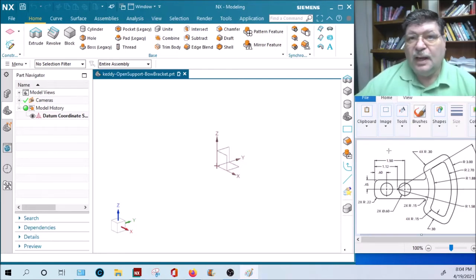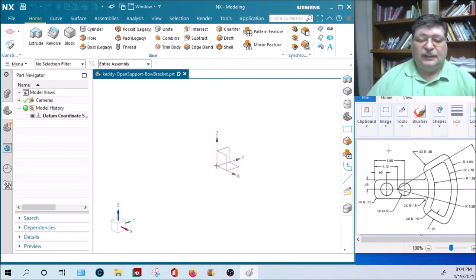Here's why. In order to just draw one line on NX, you have to make a starting point. That takes 2 dimensions, 2 constraints to start the point, to define the point. And then the other point of the line is another 2 points, x, y coordinates, or an angle and a distance, but that's 4 constraints. Now the next line, you already have the endpoint constrained that's attached to it, so the next line you only need 2 constraints on it. If it was an arc, it would need 2 constraints for that endpoint plus a radius. So lines need 2 or 3 constraints typically